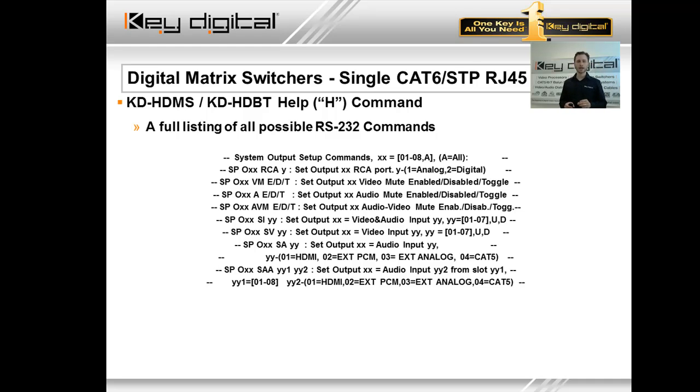YY2, we'll make that 01. That means within that card slot 3, we're taking the audio off of that HDMI connection. Okay? Let's do a quick example for HD 8x8BT, because I want to remind you on the 4x4 version, where we refer to everything as the card slot number. On the 8x8 version, it returns back to that 1 through 8, input, output, respectively type.